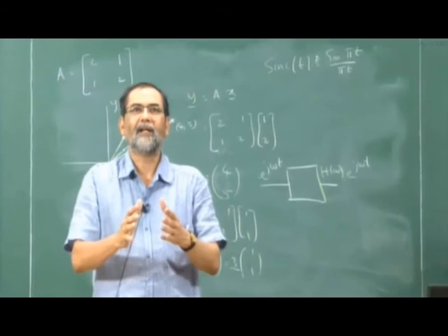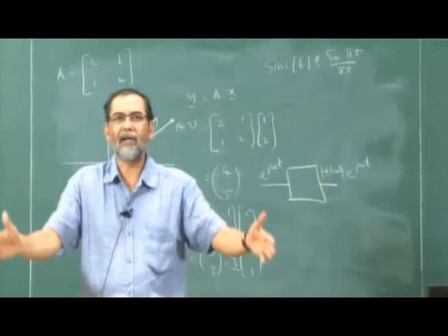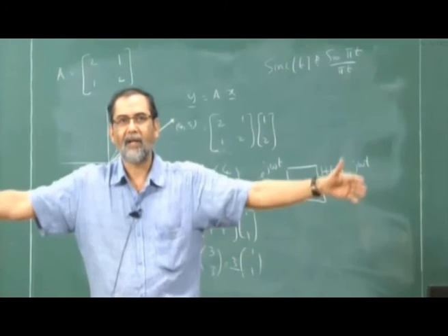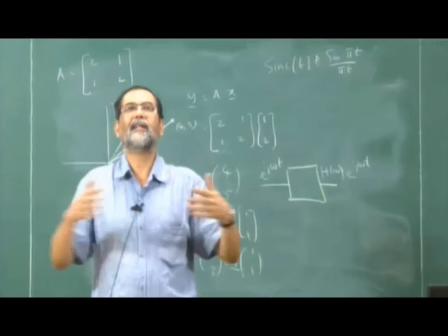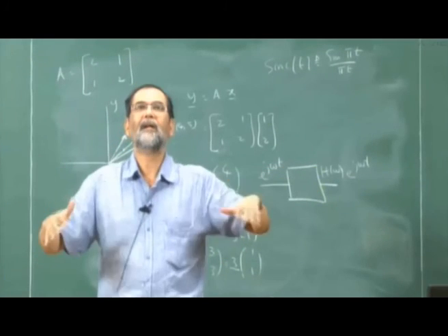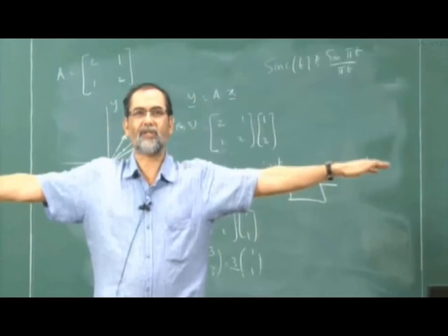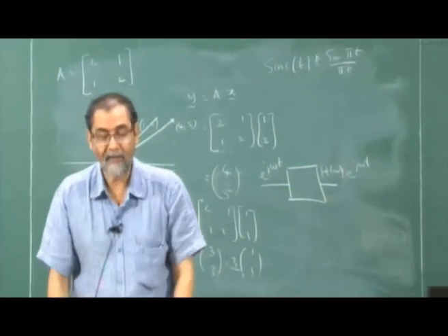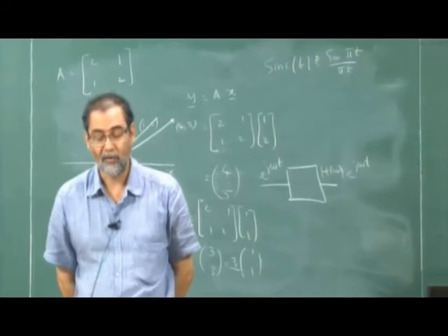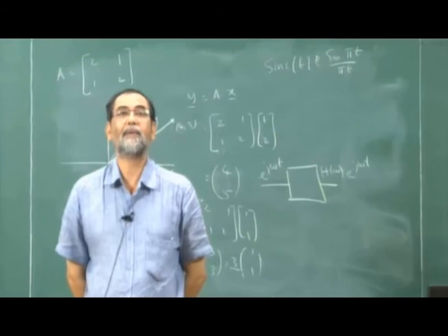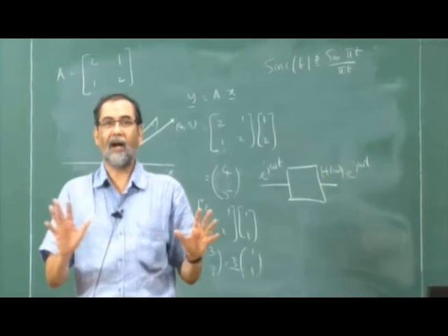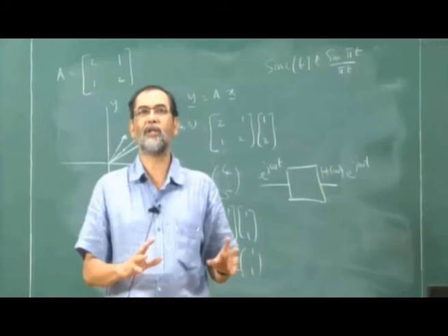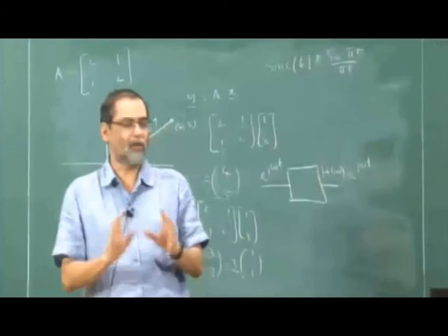When I do that, the first time this sin omega by omega goes to 0 becomes wider and wider. In the limit, it goes to infinity, meaning that the sinc function became constant, equal to 1. That's the limiting argument I used to find the Fourier transform of an impulse function, right? I didn't say sinc and so on. So I didn't use sinc as an approximation to a rect. I used a limiting argument on that.